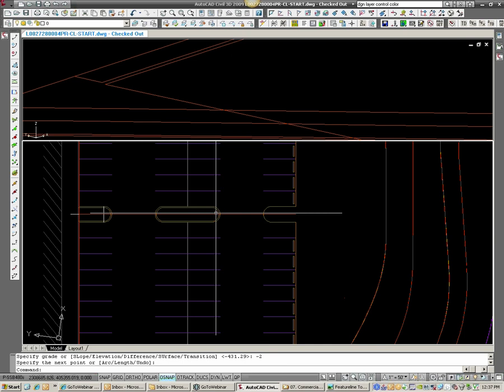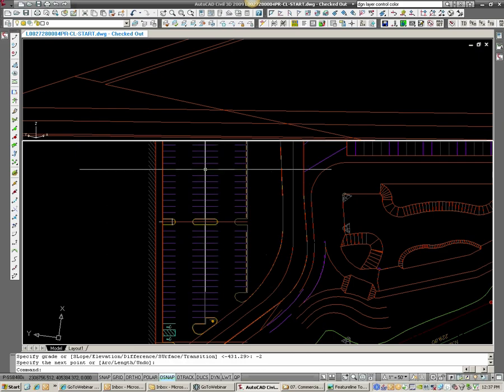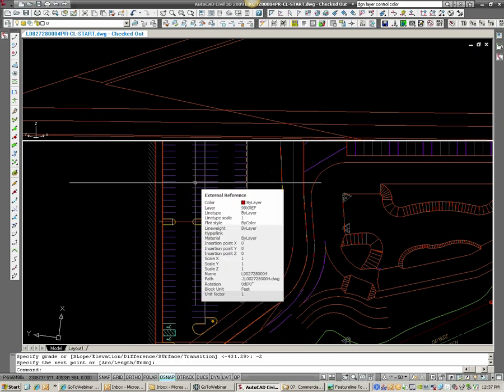contours, just let me cover this a second. You can notice we are not drawing contours. The computer takes care of drawing the contours part. Just like surveyors don't go out and survey the contours, they survey points. The computer draws the contours. Contours are not a surface. Contours are a 2D representation of a surface.